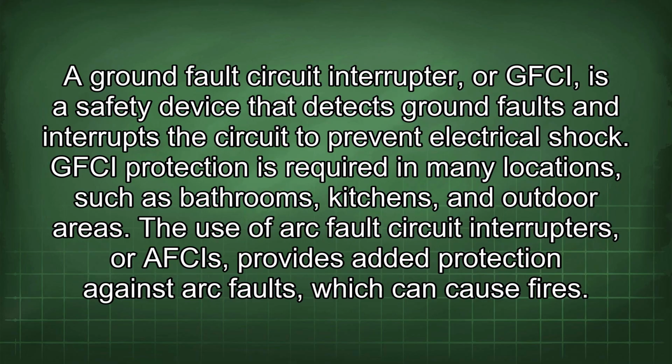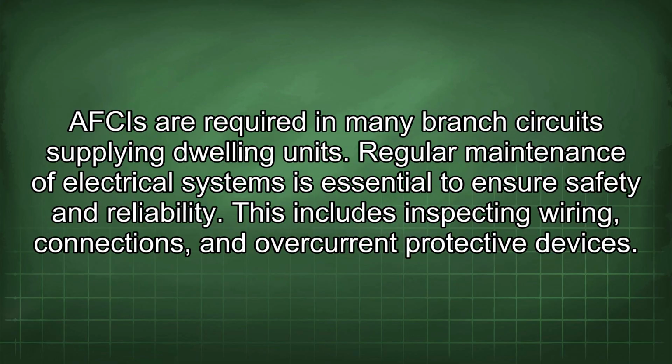A ground fault circuit interrupter, or GFCI, is a safety device that detects ground faults and interrupts the circuit to prevent electrical shock. GFCI protection is required in many locations, such as bathrooms, kitchens, and outdoor areas. The use of arc fault circuit interrupters, or AFCIs, provides added protection against arc faults, which can cause fires. AFCIs are required in many branch circuits in dwelling units.